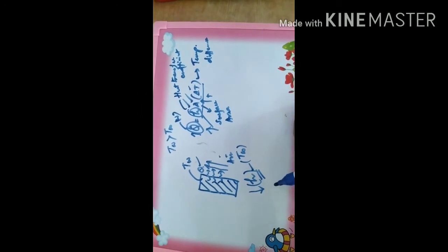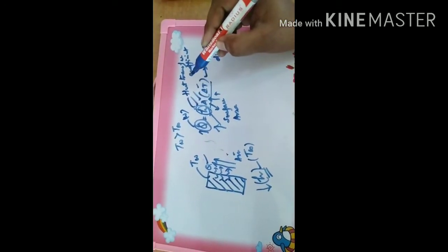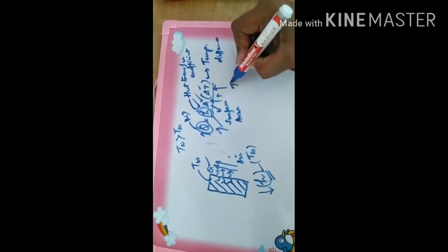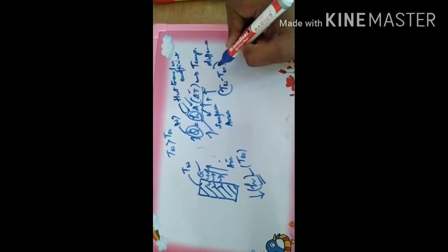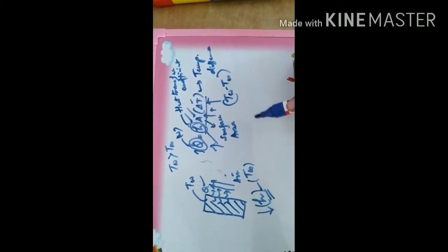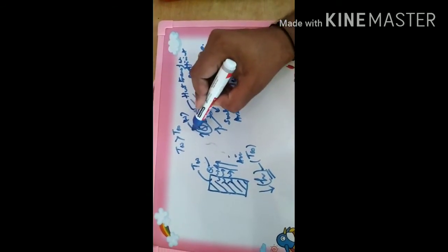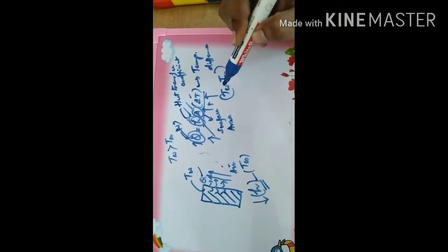Okay, but there is a limitation for this. This is also having some limitations, and this delta T here for the given example is Tw minus T infinity. Since these two temperatures are fixed values, the only option for us to increase the value of Q is to increase the value of area.